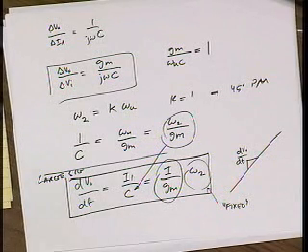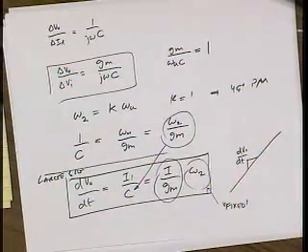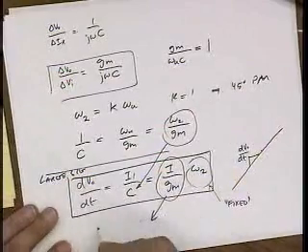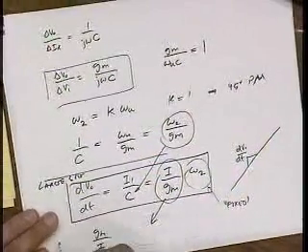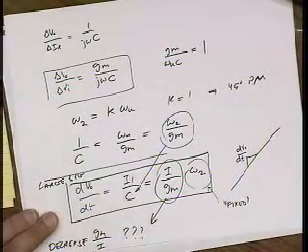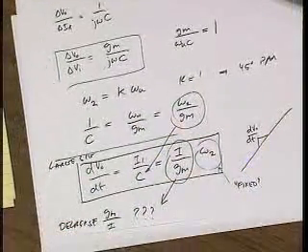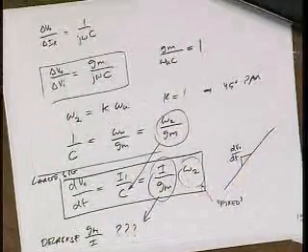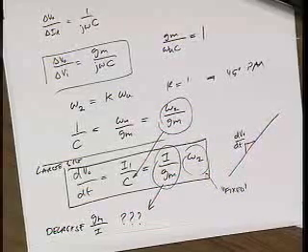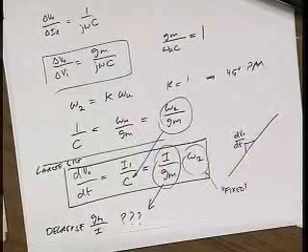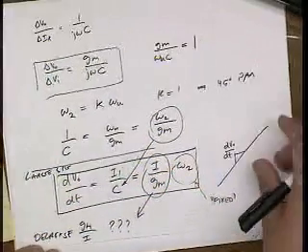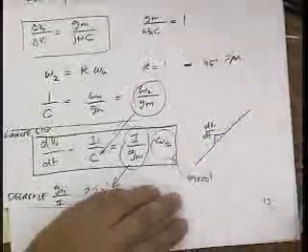And here we kind of have a funny result. It's not intuitive, right? At first, you think, what? I want to increase this? In other words, I want to decrease GM over I. Certainly we made a mistake, right? Because every other place, GM over I was a good thing, right? We wanted to maximize our GM. Now all of a sudden we want to minimize it. It seems like we've made a mistake. In fact, we have not made a mistake. A lower GM over I actually helps with slewing.